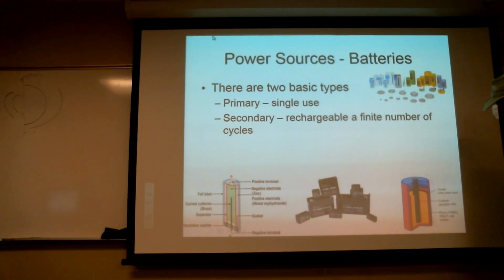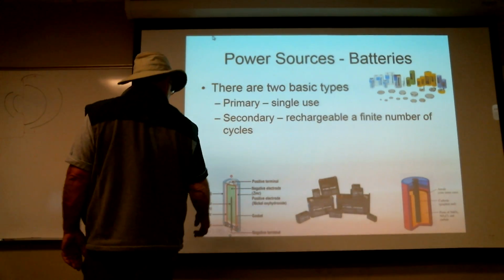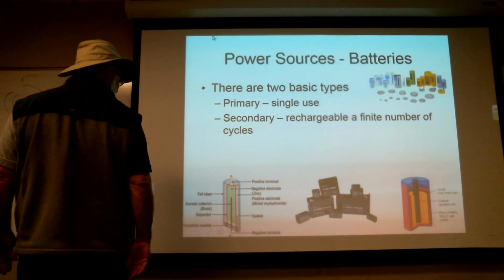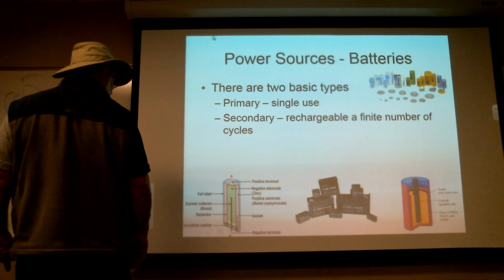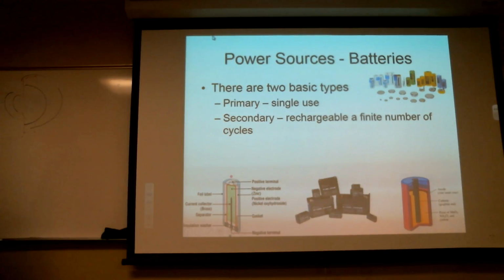The anode in this case is the outer case. Cathode, the graphite rod, is in the middle. Here it looks like a paste of nickel metal chloride or nickel hydrogen chloride. And they don't tell us what that one is. Oh yeah, they do. Internal zinc, and then a brass stud for the positive. That's interesting. So in that case, the zinc is your anode, and the brass would be your cathode.